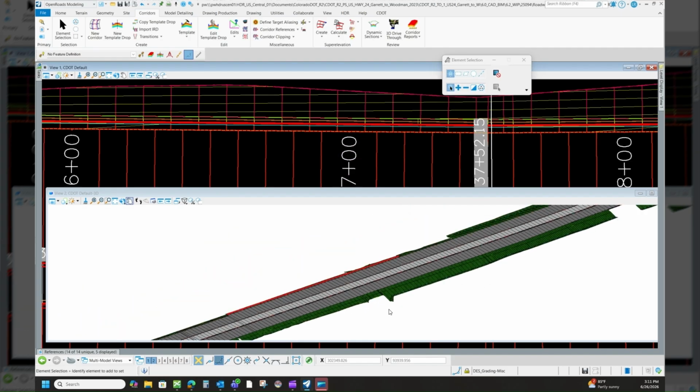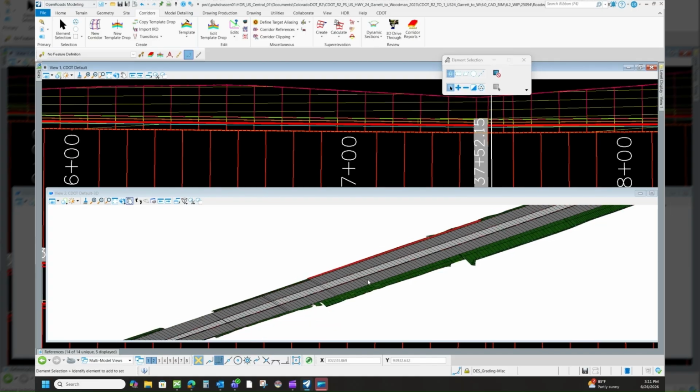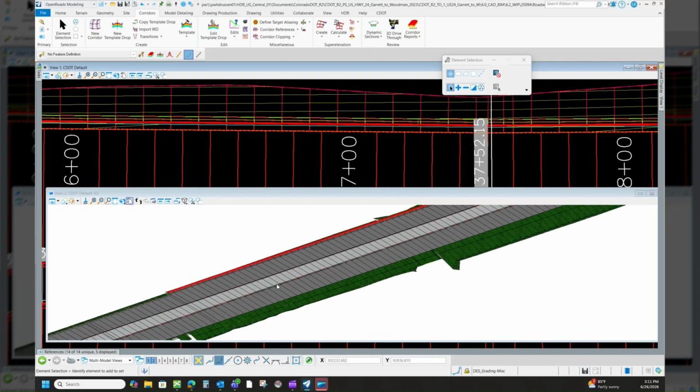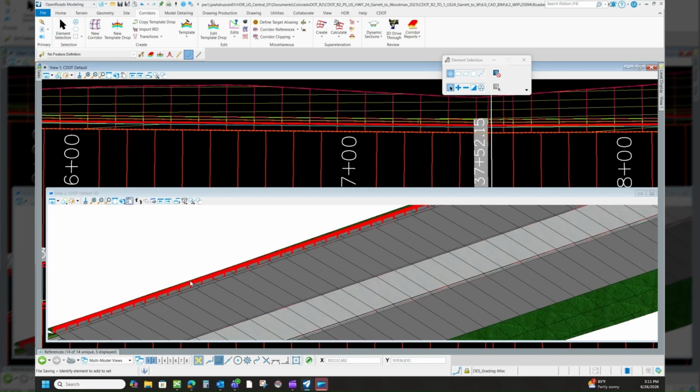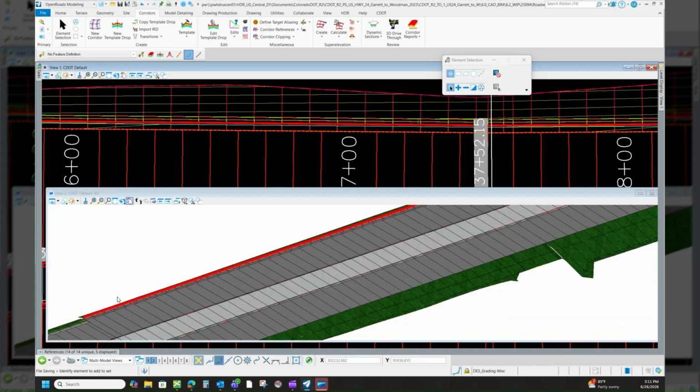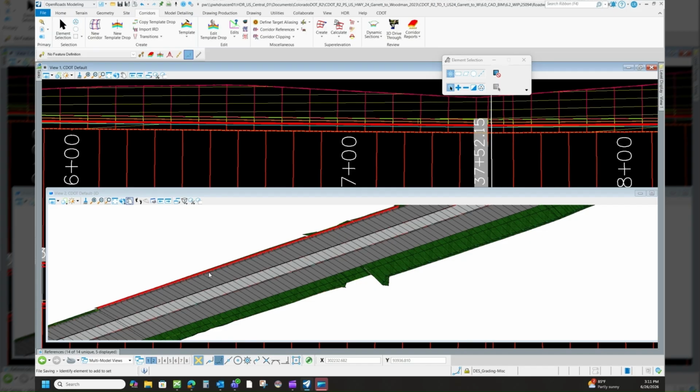My ditch control still exists. And that's one more thing: template points, how you name, how you control, the importance of it all. Same thing if I turn my guardrail off. There's not really a ditch control on this side, but if there were, the importance of it. And the importance of just simplicity.